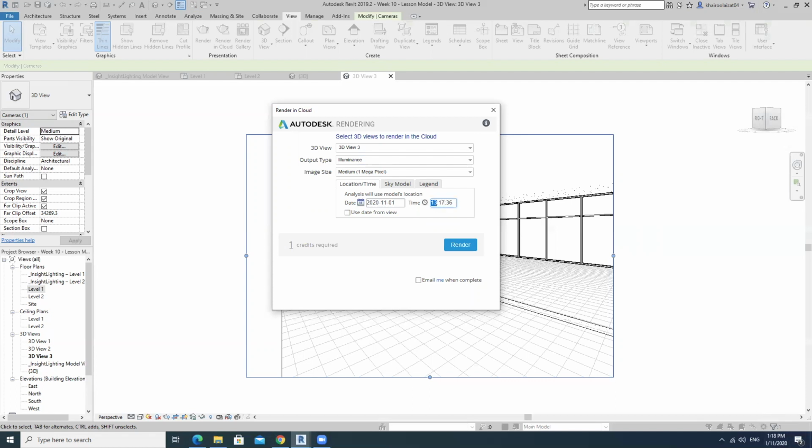I've set this time frame to 1:18, basically the current time I'm doing this recording at, 1:17. So we're going to see how the light reacts to this space. This one I just maintain as it is. Units, I wanted it to be lux, and the range I just maintain as automatic, so it will automatically set the minimum and maximum lux level.